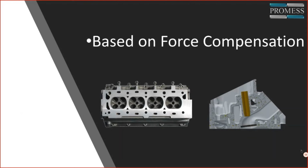An example of this would be installing valve seat and guides into an engine block. With the valve seat, you're pressing to a hard stop, but with the guide, there isn't a hard stop. You're pressing to a position in space. But because of tolerances required, and with deflection in the machine, and because the guide has a lot of surface area to cover, any change in the bore or any surface area finish that's not identical, it'll cause a fluctuation in the final force up to 6,000 pounds or more.